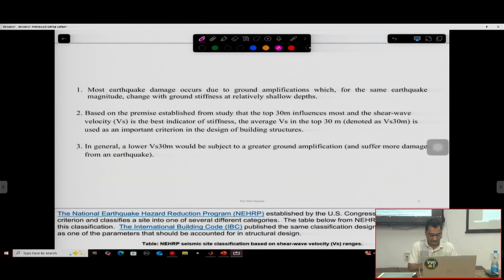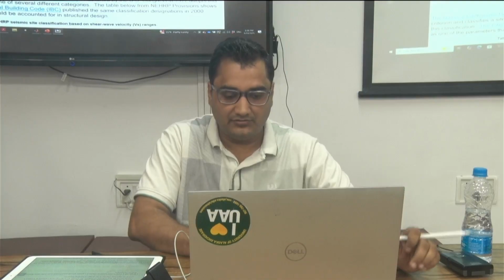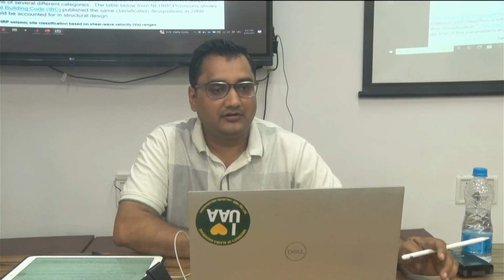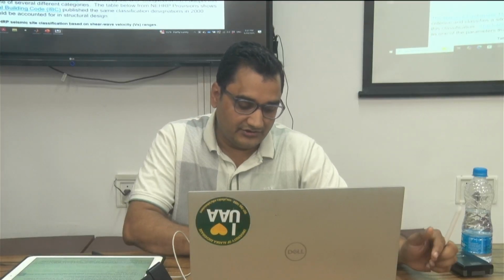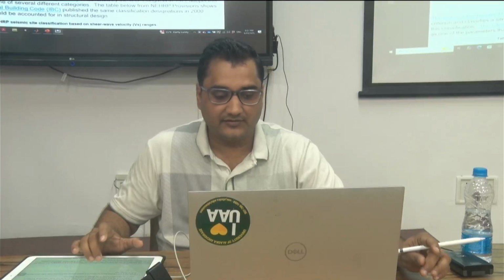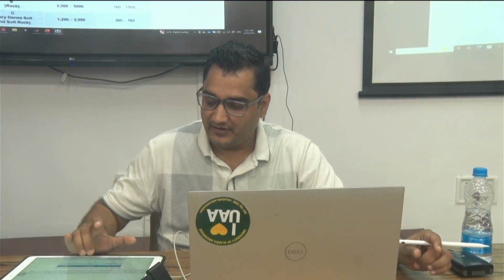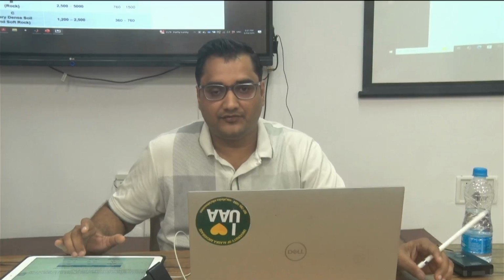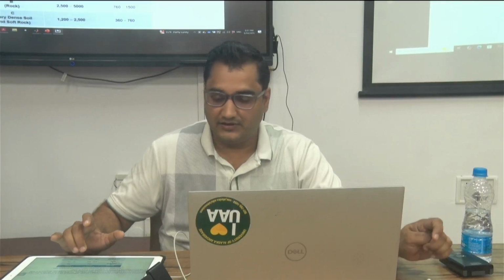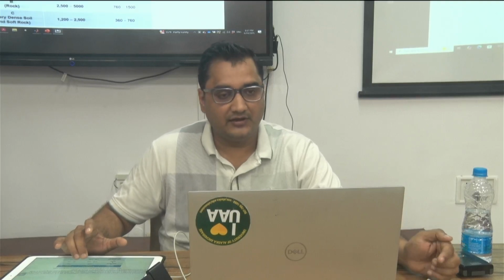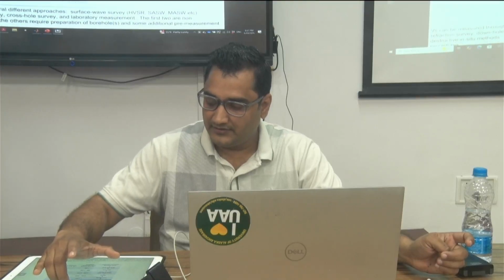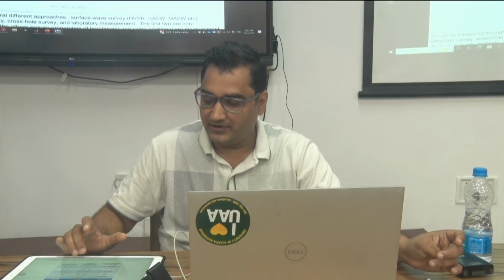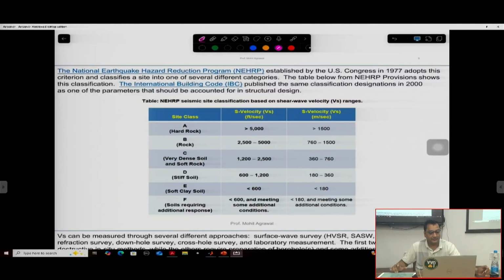So in the previous lecture, we did talk about site characterization and a couple of site characterization techniques. The shear wave velocity is the best indicator of the stiffness, and our aim is to find out the shear wave velocity for the top 30 meters in the ground in order to design the building structures safely in an area. And this is the NEHRP program. They have proposed some guidelines for classification of the site class.